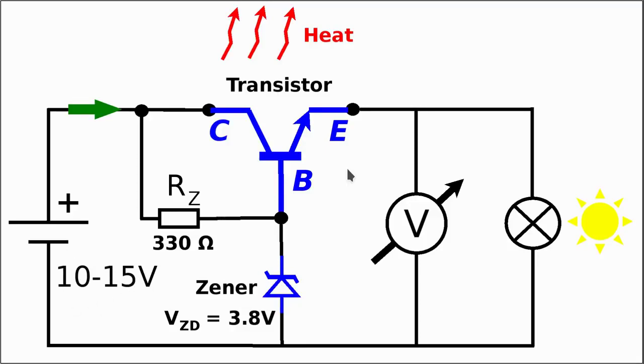At this stage we have to ask what could we do to improve the stability of this power supply, in particular the output stability. Before we make any changes to the current circuit, let us first think about what could potentially be missing or what could be wrong. So here the input voltage, we know it will change. This is why we are using this Zener diode to provide a relatively stable reference voltage.